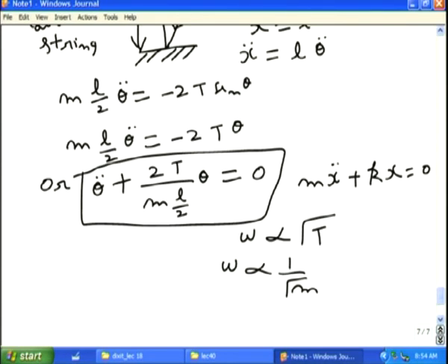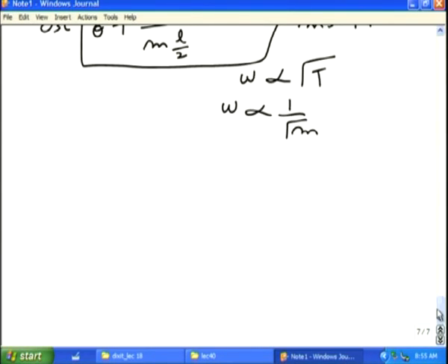So, you see that we study the spring mass system because other systems also generate the differential equation in that form. So, therefore, this equation becomes very important. Of course, here we have considered only the linear system, linear differential equation. Here k is not changing, is not a function of x. If k is a function of x, then the equation will become non-linear and you will get non-linear vibrations.